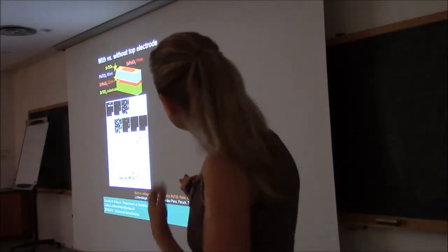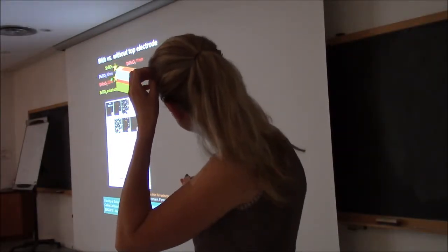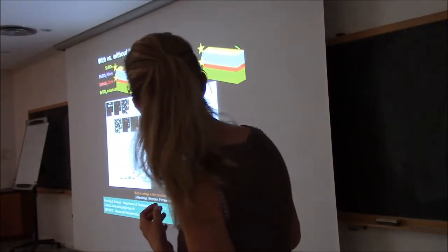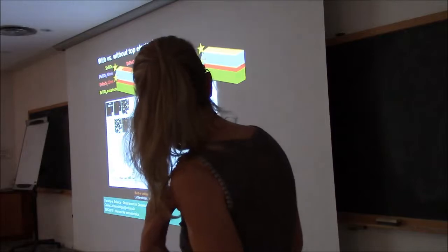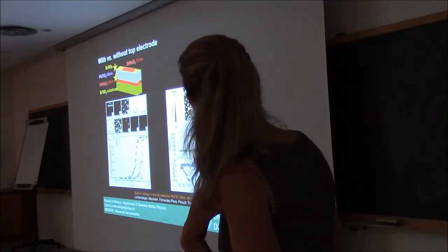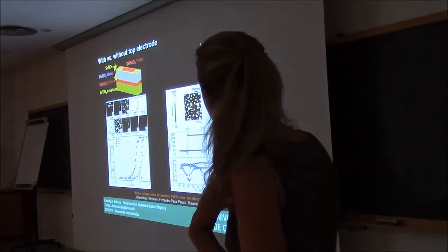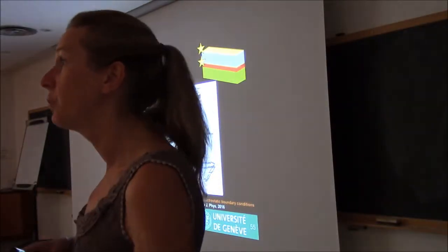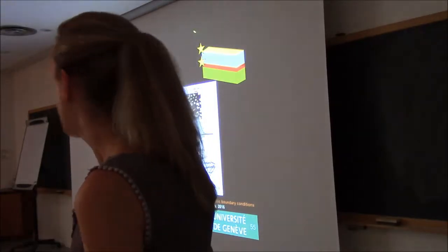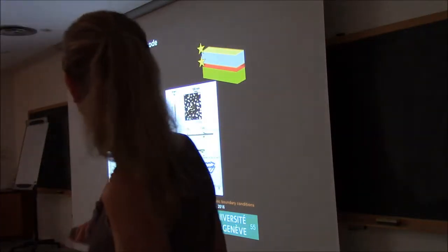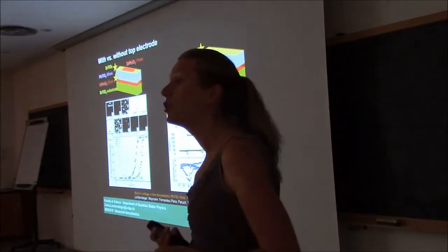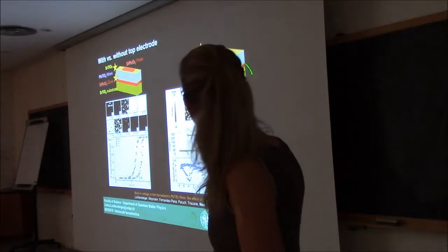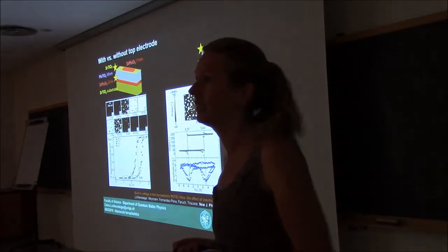And if you compare, so this is a 50 nanometer PTO with 2 nanometer top and bottom STO with the top electrode. If you remember from the previous slides, the same material without the top electrode had something that was more centered, with 50% up and 50% down domain. So the presence of the top strontium ruthenate electrode has an effect on the built-in field and has completely shifted the loop. We started with a material that was polydomain, but with the strontium ruthenate, it's monodomain.